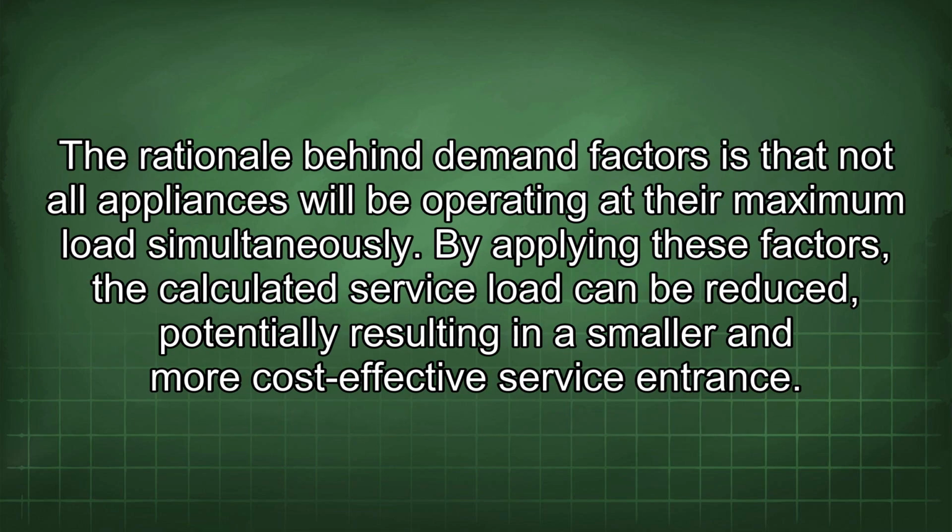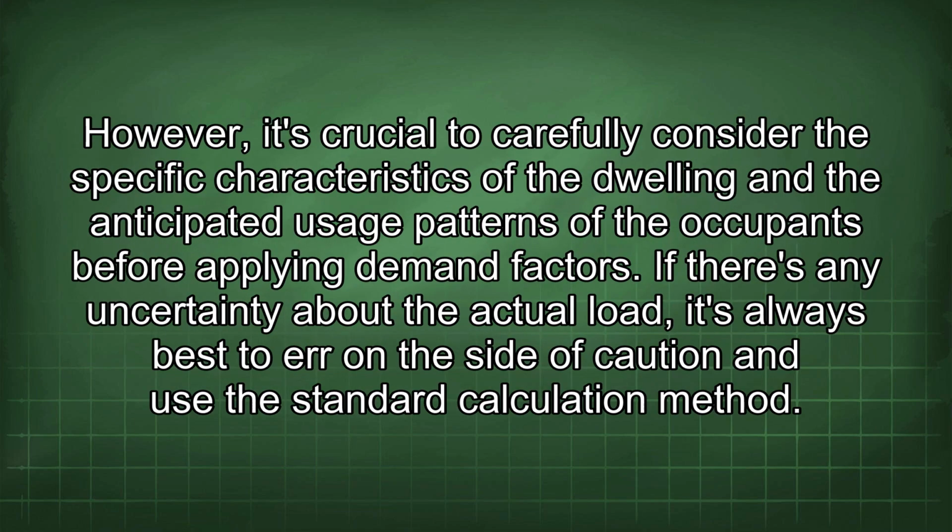The rationale behind demand factors is that not all appliances will be operating at their maximum load simultaneously. By applying these factors, the calculated service load can be reduced, potentially resulting in a smaller and more cost-effective service entrance. However, it's crucial to carefully consider the specific characteristics of the dwelling and the anticipated usage patterns of the occupants before applying demand factors. If there is any uncertainty about the actual load, it's always best to err on the side of caution and use the standard calculation method.